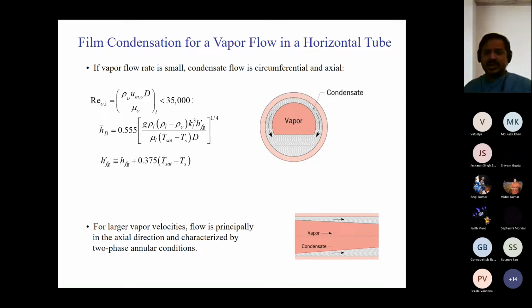Okay, this is not a static vapor. The vapor is actually flowing through a tube. So as you would expect that initially it will be vapor and then there will be a film, condensate film that will form on the inner walls of the tube. And if you look along the streamwise direction, the vapor core will slowly reduce and this film is going to form on the walls.